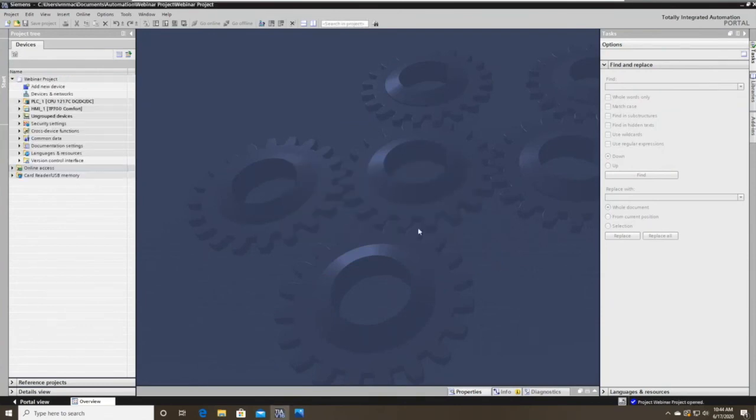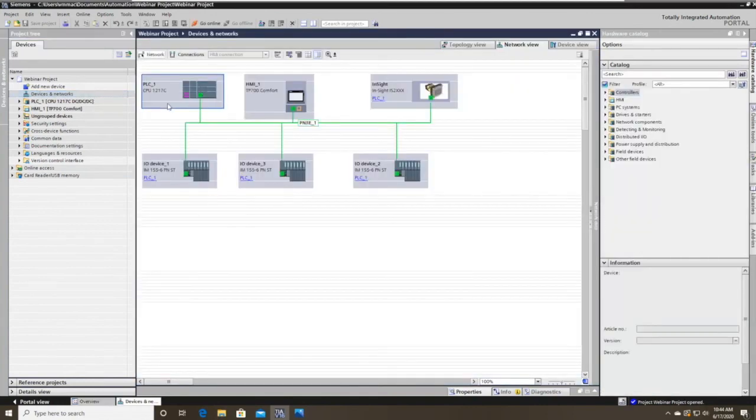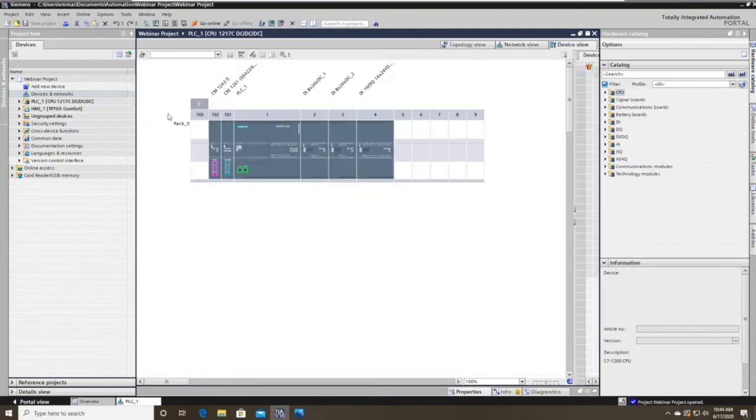Yes, absolutely. You can specify a separate subnet with those additional communication cards. Oh, okay. Is that a relatively new feature, or we were under the impression you couldn't? No, that's been a feature. It just depends on the setup. So if you have a setup with just the S7-1200 alone, it's not going to allow you to do that. If you add an Ethernet card onto it, though, it should let you do that. I'm going to try it right now.